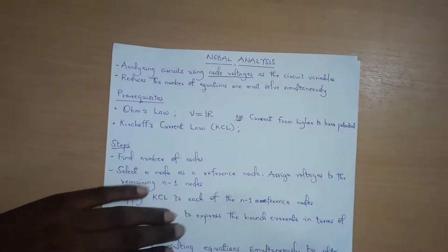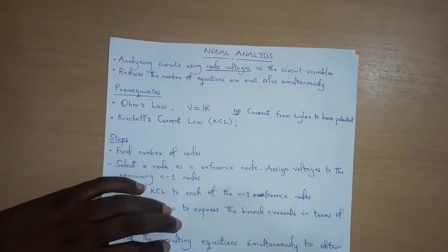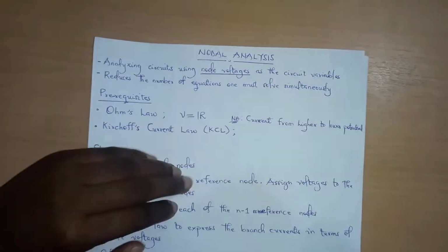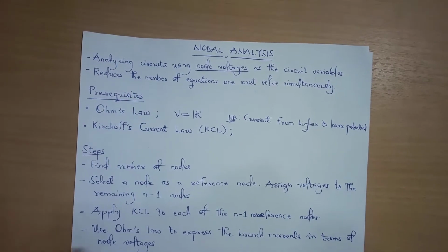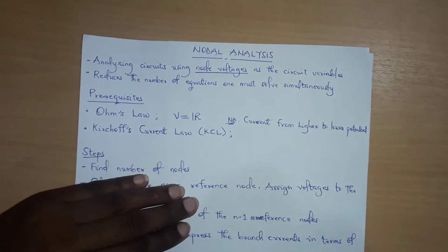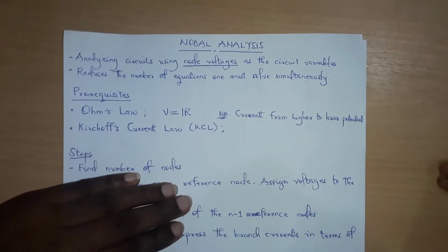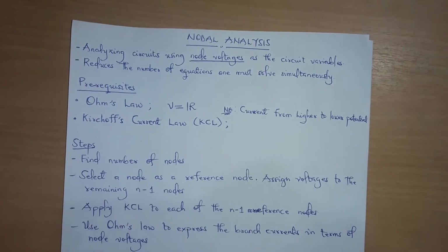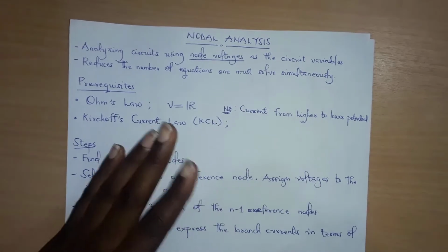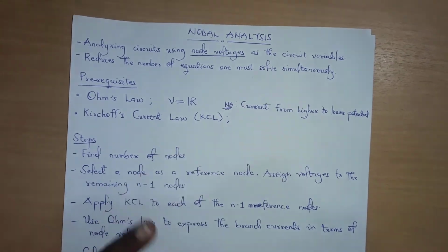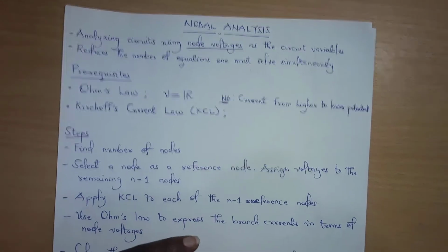Welcome to today's tutorial video on nodal analysis. So basically, nodal analysis is all about analyzing circuits with node voltages as the circuit's variables. And we do nodal analysis because it helps us to reduce the number of equations that we must solve simultaneously to be able to analyze the circuit.